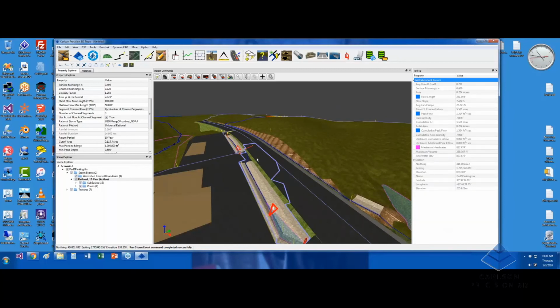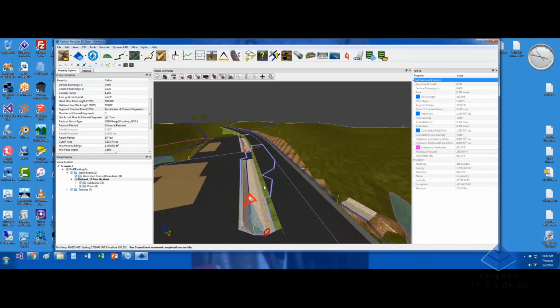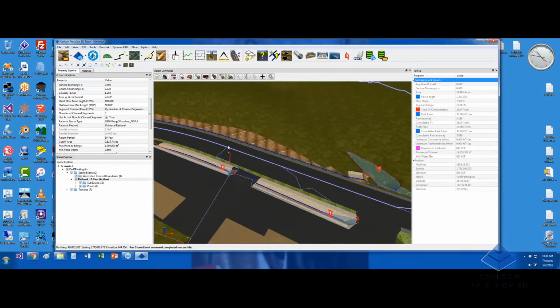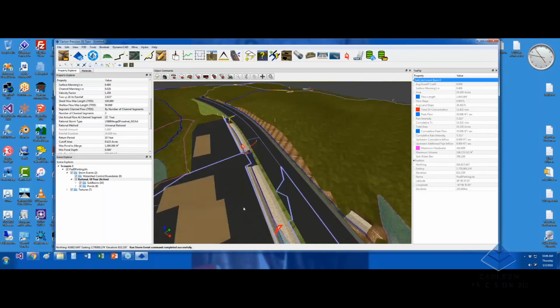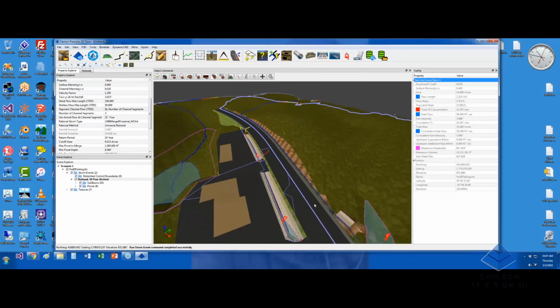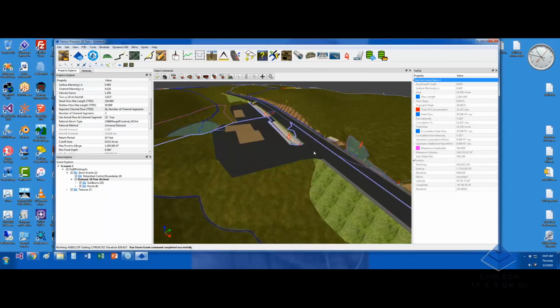Now, one thing that we can all see, since this is a downhill and a super, we're in a little super elevation situation here, coming along a spiral. And I would prefer this boundary to be straight, but there's two boundaries, right? There's this subbasin out here, which is subcatchment basin 4. If you look at my tooltips, as I move my mouse into a subbasin, we give you all the information for that basin.